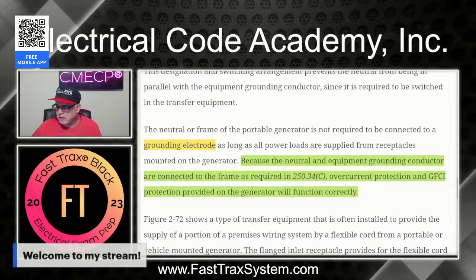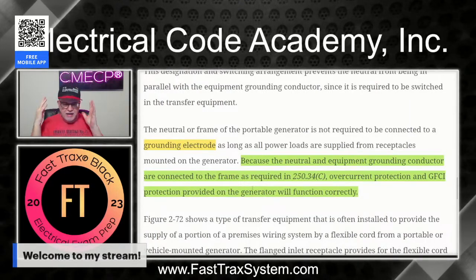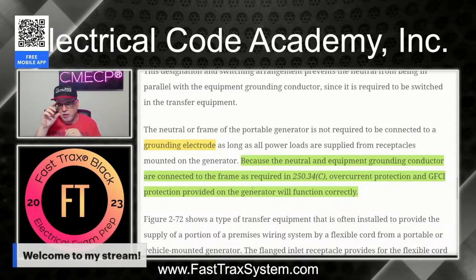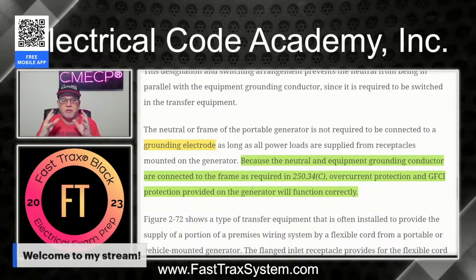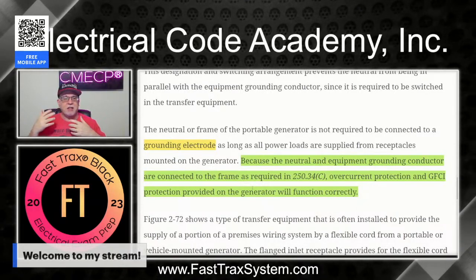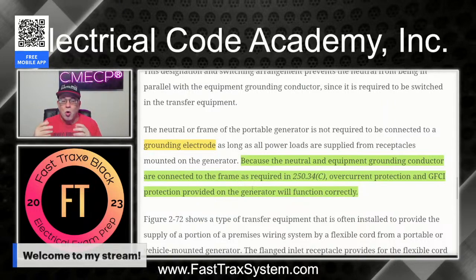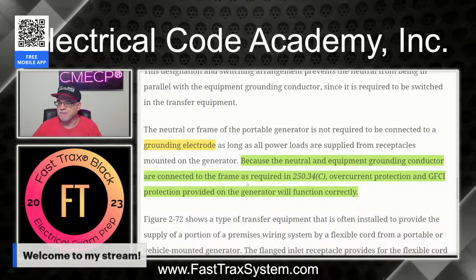Okay, so this is a generator where you have the bonding jumper in it. Everything's bonded. The equipment ground terminals for the receptacle is intimate with the metal framing of the generator, which is intimate with the neutral point on the windings of the generator. If that's all done, and all the receptacles supplying the loads are cord and plug on the generator, or the equipment itself that's supplied by the generator is on the generator, then I do not have to have any electrodes. We've already established that, right?